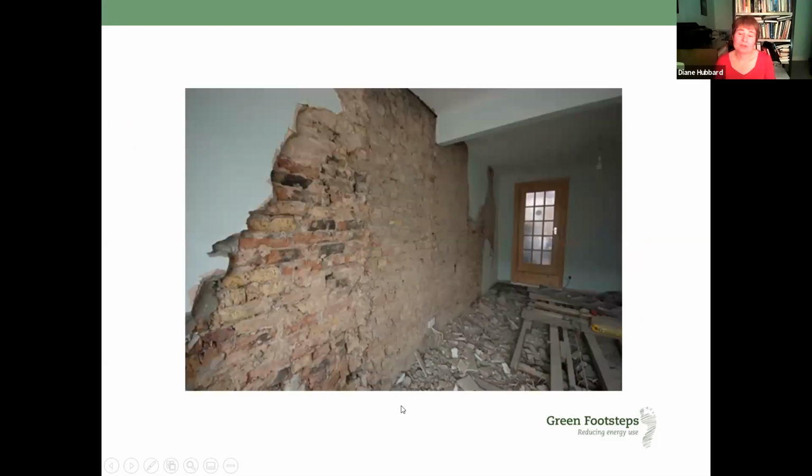So if we think about our older buildings, one of the key things we need to appreciate is it's the presence of the plaster that is keeping the air out. All our common building materials, so blocks, standard bricks, stone, rubble construction walls, they're all air permeable, and it's this layer of plaster on the inside that reduces the air movement. So if you're thinking about air tightness in your home, you need to start thinking about the places where this plaster is not continuous or where it's broken.